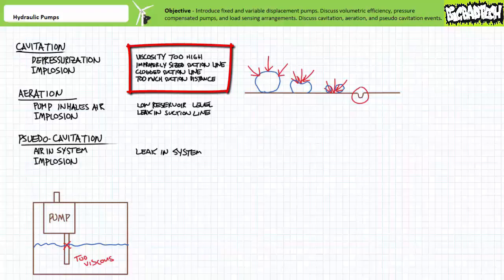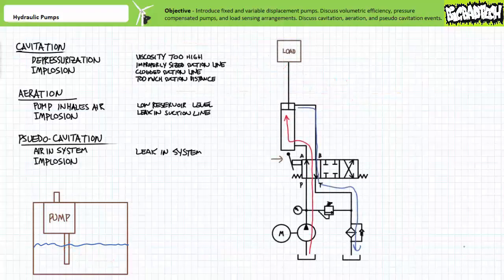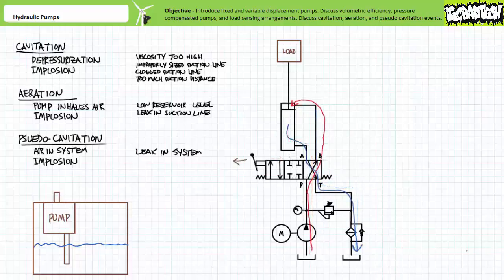Too often, technicians race to replace the pump only for these problems to reoccur. Cavitation is not exclusively a pump phenomenon, but can also occur inside valves and actuators. Consider a double-acting cylinder lifting a heavy load against gravity, or tipping or tilting an overrunning or negative load. When the cylinder lifts the load, pressurized fluid supports it. When the directional control valve is shifted into the cross-connect position, pressurized liquid no longer supports the lifted load, and the load and cylinder crash to the limits of travel, and perhaps beyond.